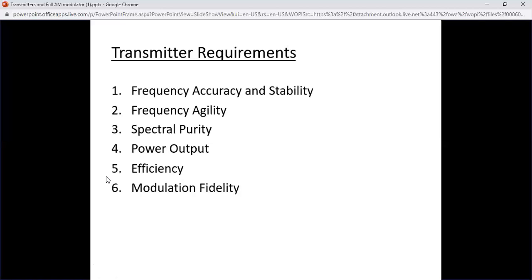In calculating the energy cost, the overall efficiency is what should be considered, and it's the ratio of the output power to the input power. The overall efficiency is reduced by losses in the power supply and the tube heater power.